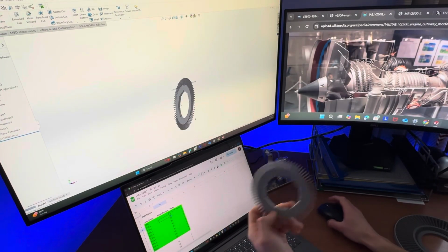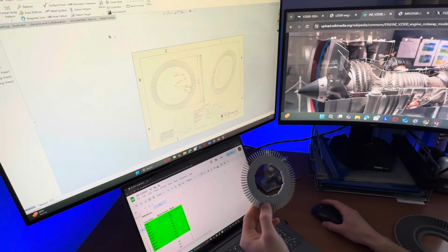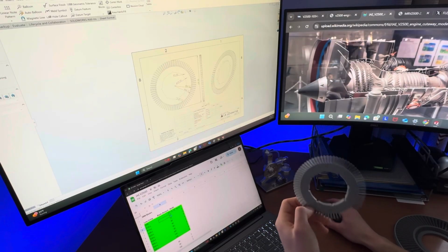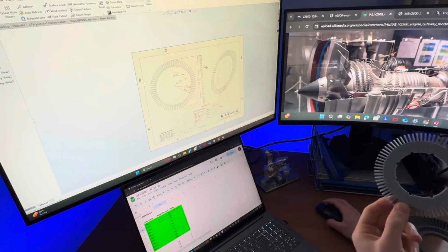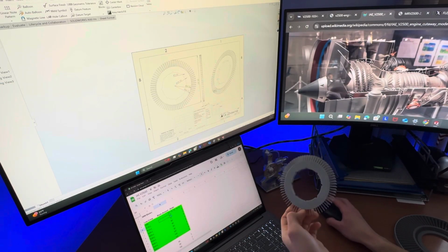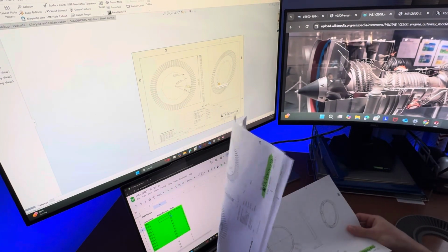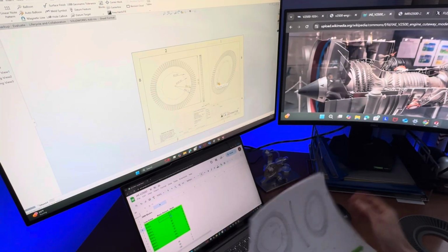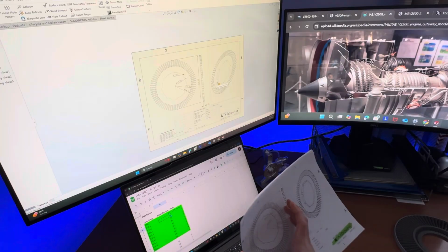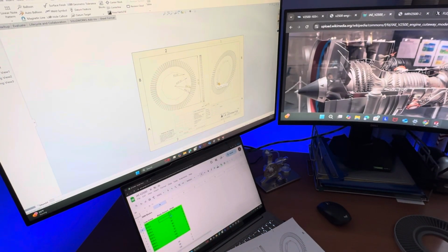This is the part I designed, and I made a drawing on SolidWorks where I added the dimensions with this tool right here. This is a radius of 29 millimeters, and it allows you to make the sketch and print it out. So I have a bunch of them right here, and this is really good because I use the dimensions from one part to make the next part, and the next part, and to design this thing as a whole, to make sure everything fits together correctly.